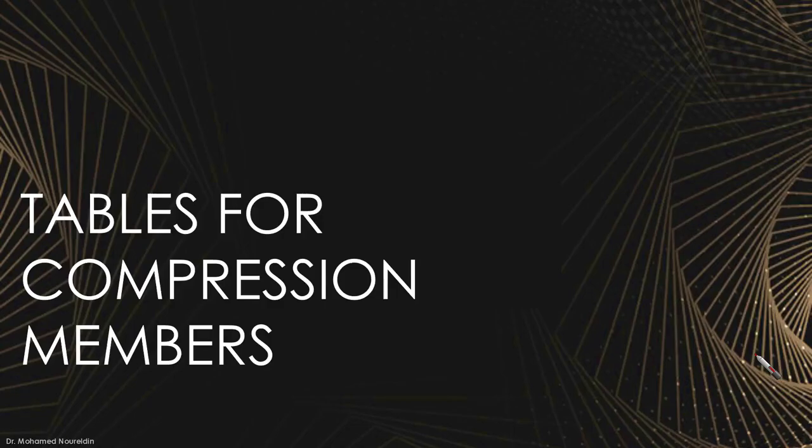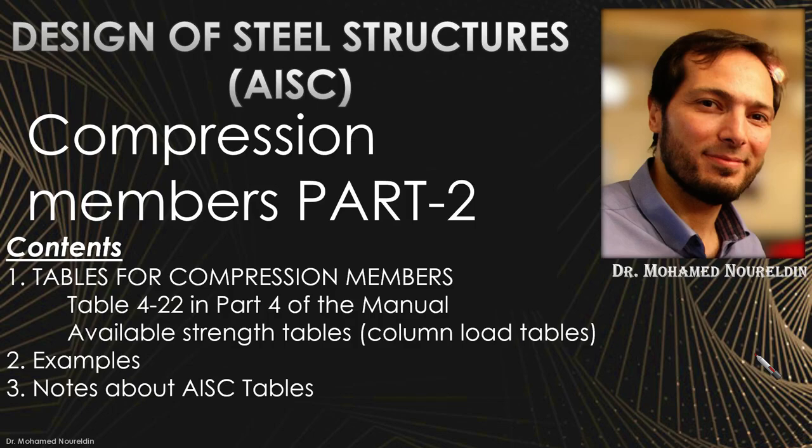Now you are able, after understanding this video and going through the main steps using your manual, to use the column tables for compression members efficiently, whether it is table 4-22 in part 4 or the available strengths tables, which we call column load tables.